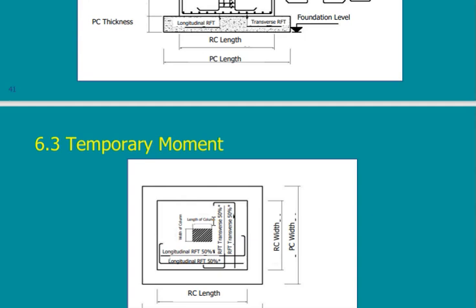I use part of the steel to be maybe covering an area, and then the other will be covering a bigger area, and so on, so that if I check the section of the beam in the middle, it will contain 10 rebars. If I check the section of the beam near the columns, it will be maybe 5 rebars or 6 rebars. So I managed to reduce 4 rebars as a way to reduce the cost.